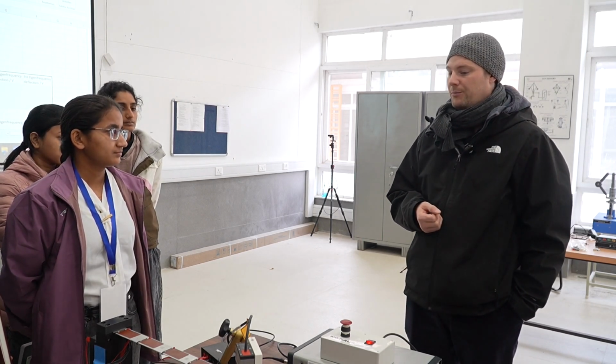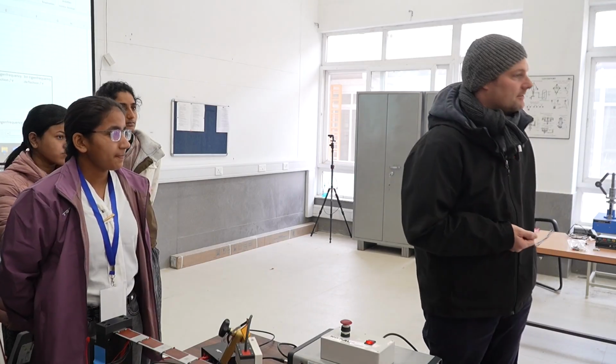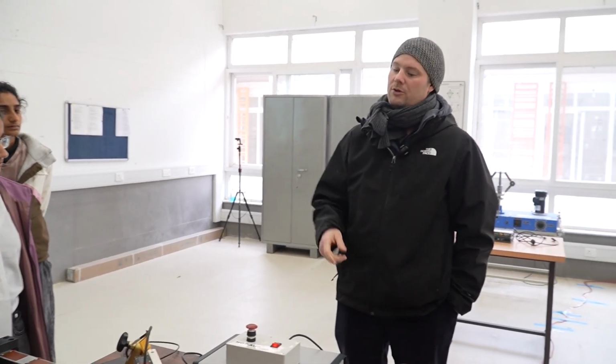So this is what we can do, but more precise, and I think still until today, for a modal analysis of an aircraft, you would really do a single frequency excitation. Attenuation, yeah. And this you do by using a sine, so a harmonic signal, and then you slowly change or increase the frequency, and you look at what happens in the experiment. So this is what we will do now.